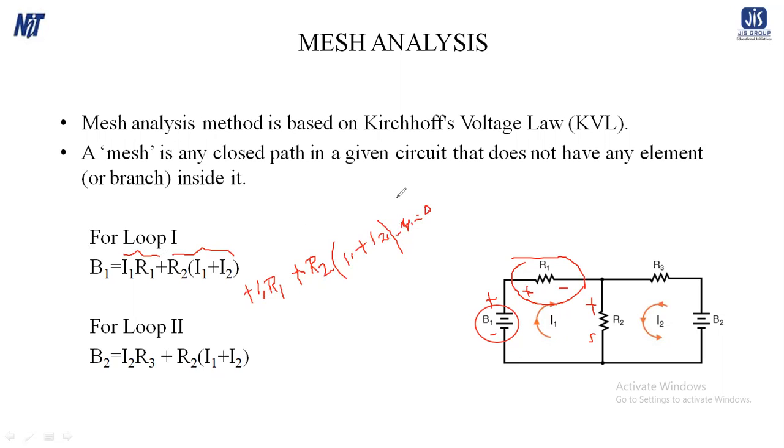So you can write V1 equals I1 R1 plus R2 into I1 plus I2. In this way we can develop the first equation of loop or mesh 1.